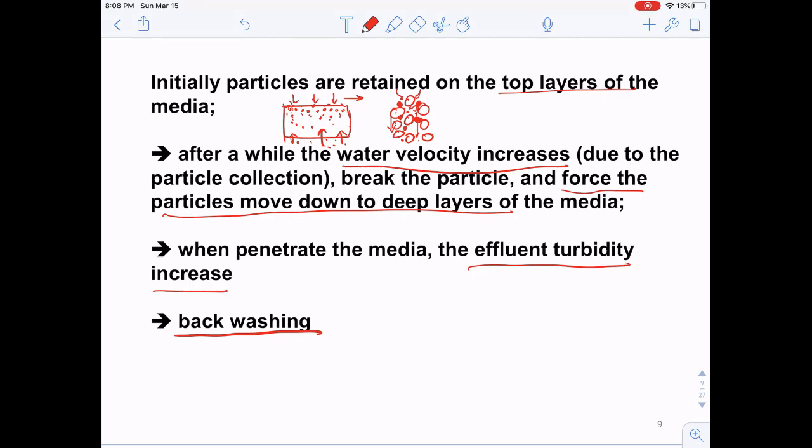And because of that, as you can think, let's say we're a manager of a water treatment facility. Can we just build one filter for the purpose of filtration? No, right? Because water treatment is always a continuous process. If we realize that the filter is contaminated or there are particles escaping from the filter, then we need to use backwashing to clean these filters.